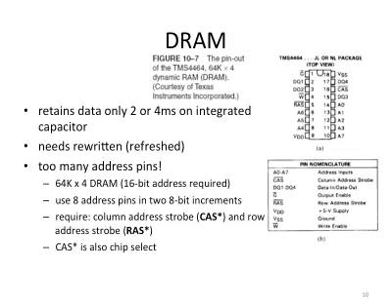So these 16 address lines are divided into 2 halves, and one half has 8 lines. We supply the first 8 in the first cycle, and then the second 8 in the next cycle. And we give them names. The first 8 is called the row address, and the second 8-bit address is called the column address.